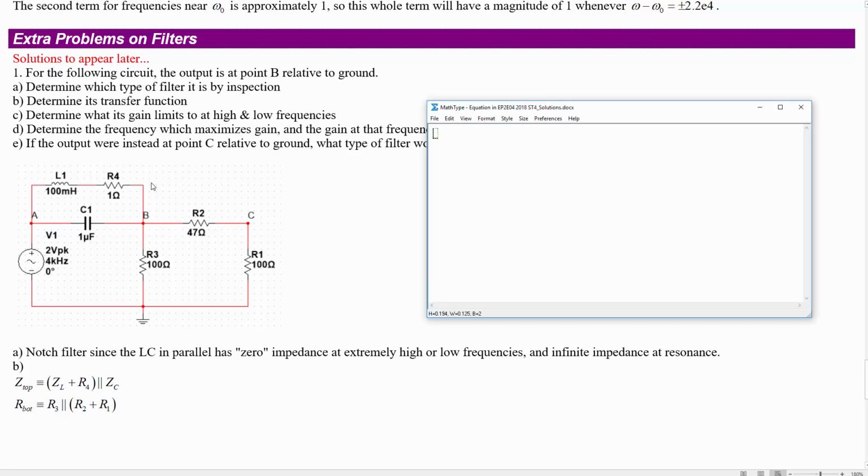So then the transfer function H is going to be equal to, by its definition here, voltage at B divided by voltage in, which is actually the voltage at A. So we've got, by a voltage divider, it's going to be the resistance of that bottom network divided by R bot plus Z top. Okay, so substituting in what we found there, we could work out those a little bit more maybe.